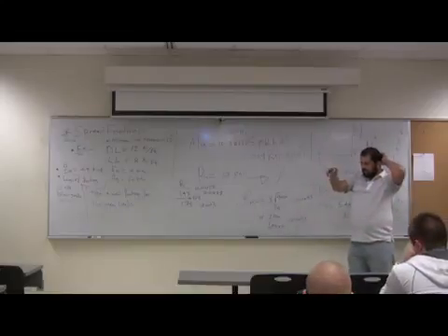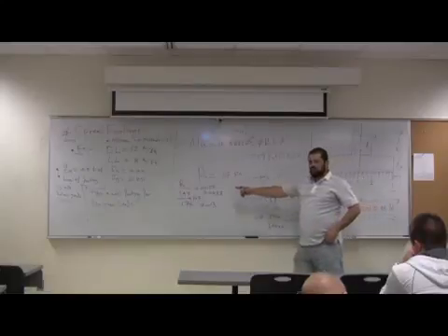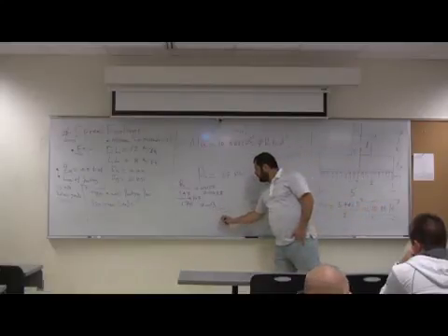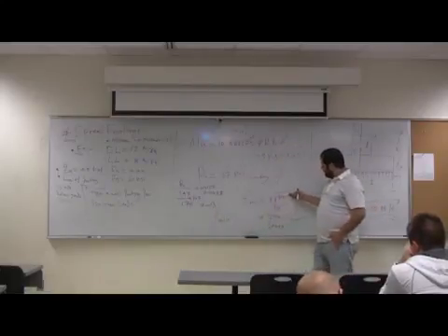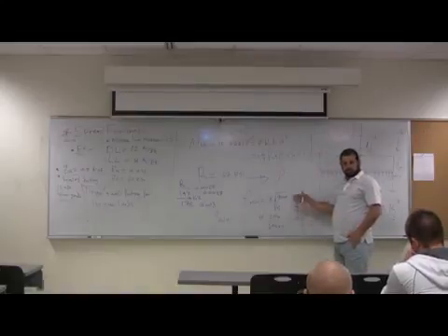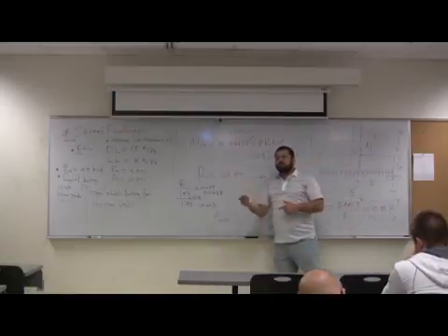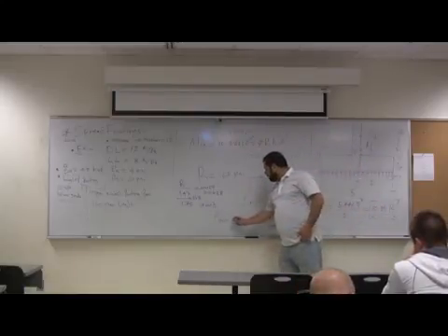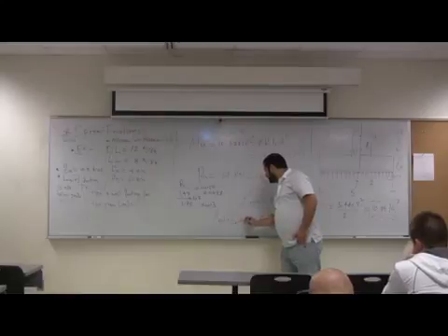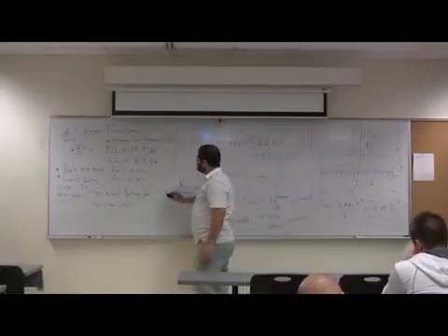You have them in the design aid, or you can calculate them. So these are less than rho minimum. We use rho minimum. By the way, rho minimum is the largest of those. That's the minimum you can use. Equal 0.0033. Now what's As?